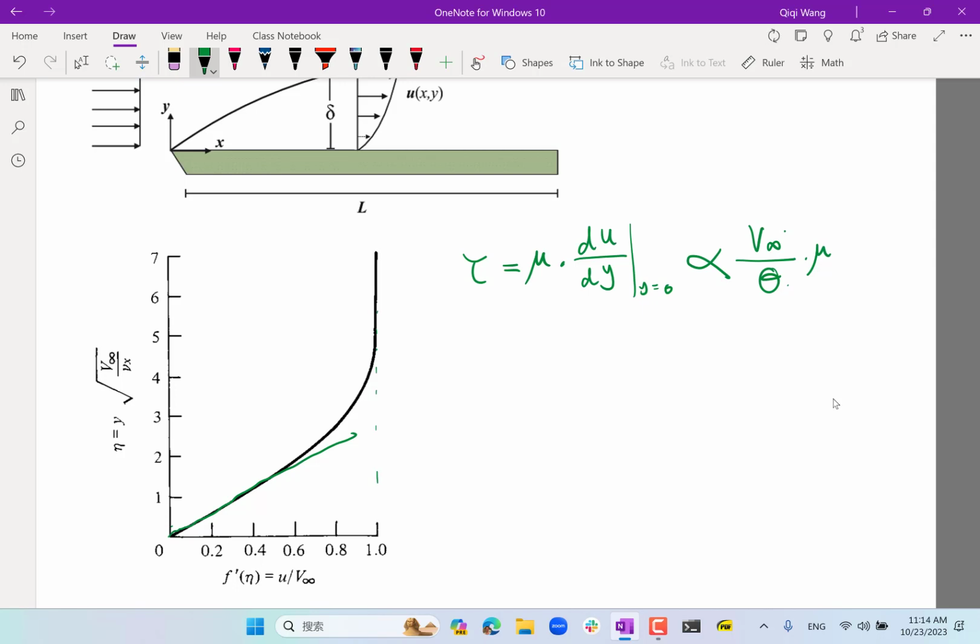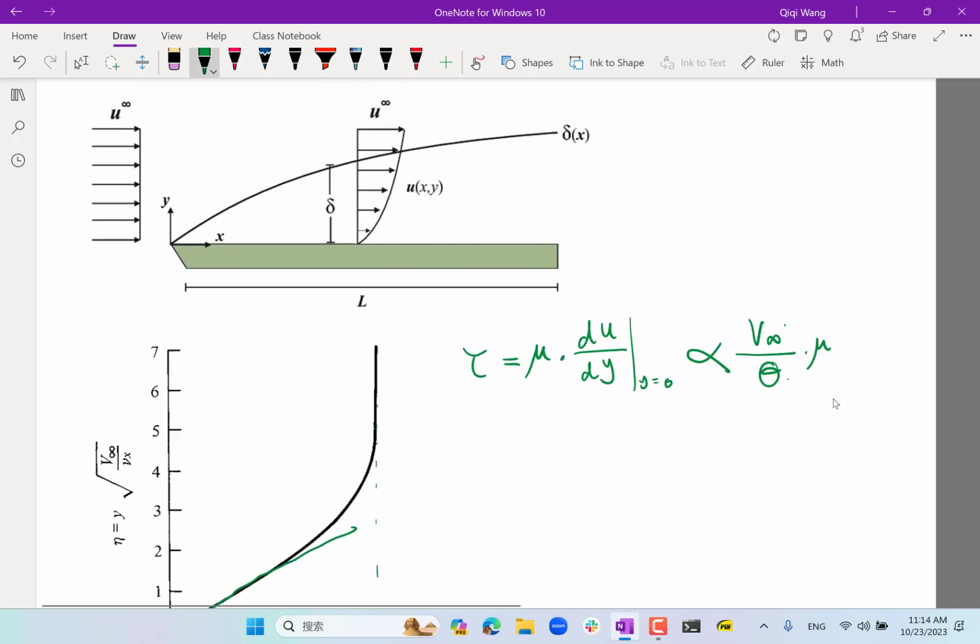All right. And through a momentum analysis, so remember the control volume we did, right? We did a control volume that follows a streamline, and we calculated how much momentum defect, how much loss of momentum this part has relative to x equal to 0, right?